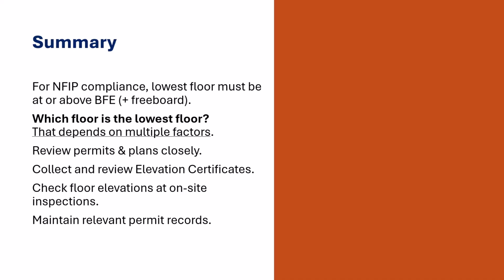Checking those floor elevations at on-site inspections during construction can help you avoid a potential violation reaching finished construction stage. As always, it's important to maintain relevant permit records for sound floodplain management purposes.